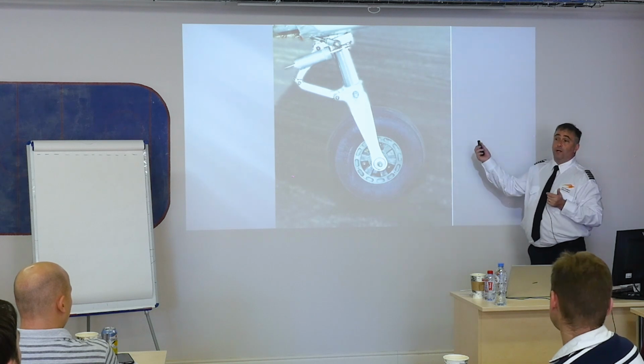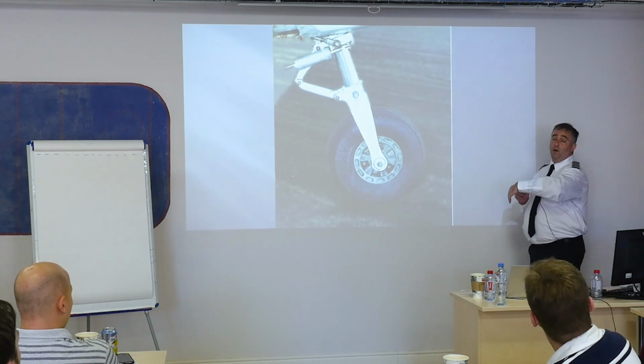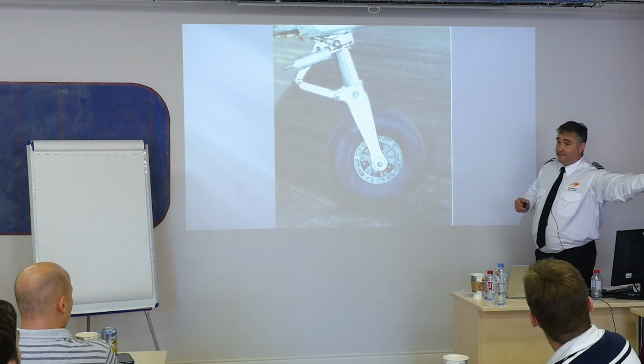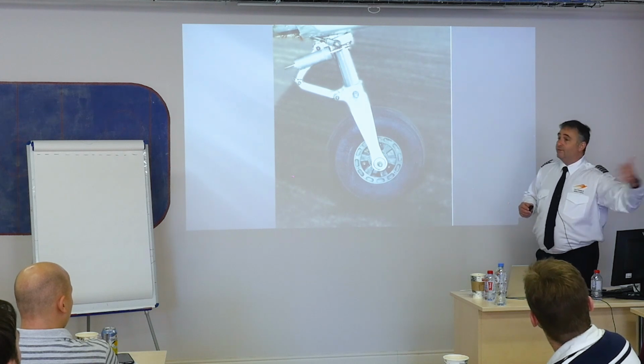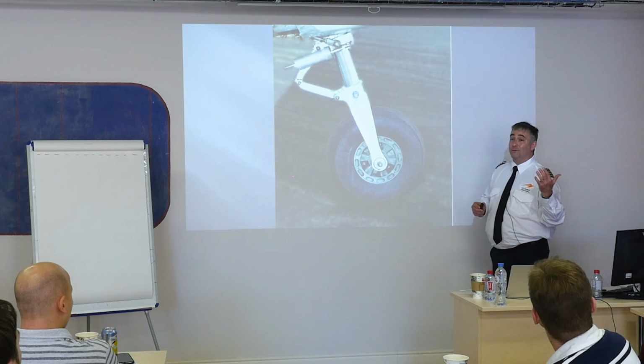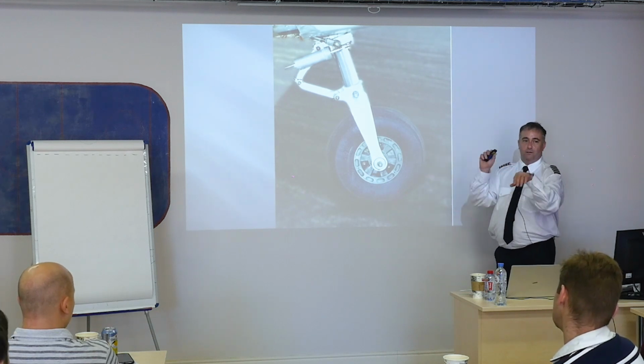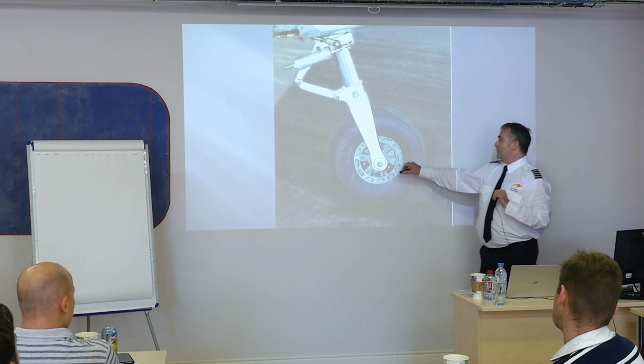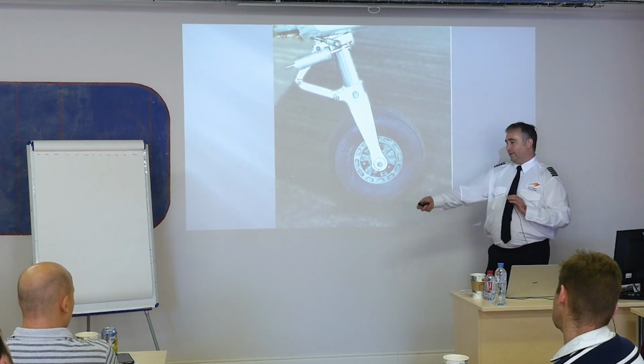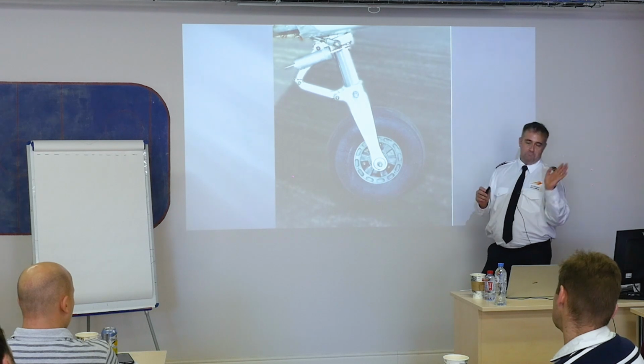If you've looked at an airport diagram, you have almost 1.5 miles of taxi to get out to runway 9. You've got a long ways that you're taxiing before you get out there. That's a long ways of riding brakes if you're trying to steer it with differential braking. If you're trying to steer it just with the nose pedal and a little bit of power, then that's perfect.